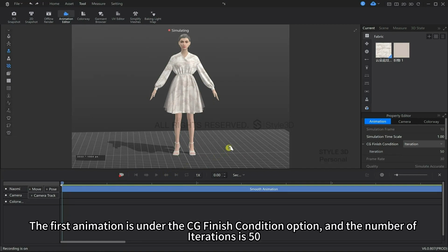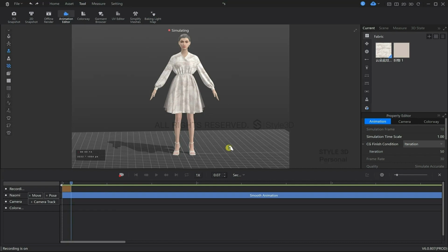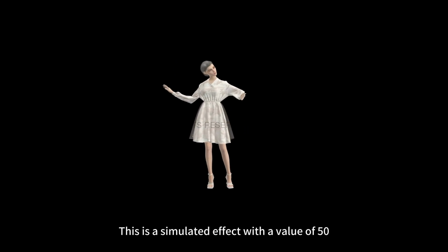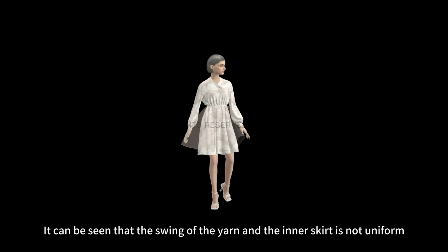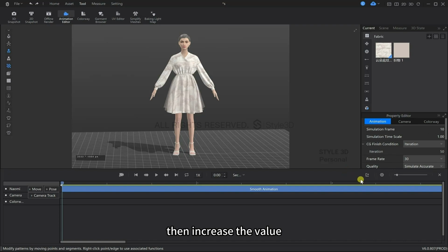The first animation is under the CG finish condition option, and the number of iterations is 50. This is a simulated effect with a value of 50. It can be seen that the swing of the yarn and the inner skirt is not uniform. Then increase the value. Adjust the number of iterations to 100. Add animation. Click to record.